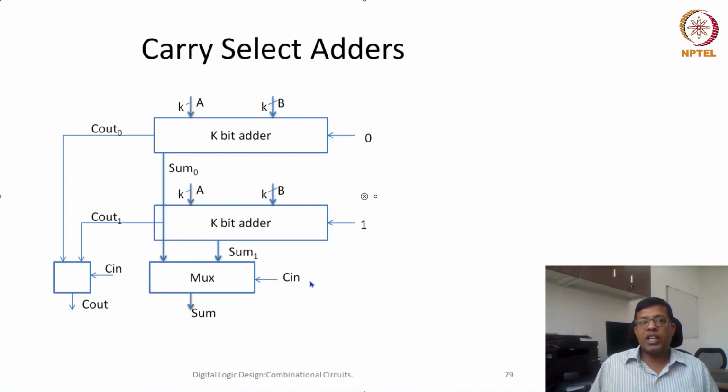We can go ahead computing the addition, and in parallel there could be another adder doing its work so that it can generate C in, and when C in is generated, then we can create the output and see which one to be selected.